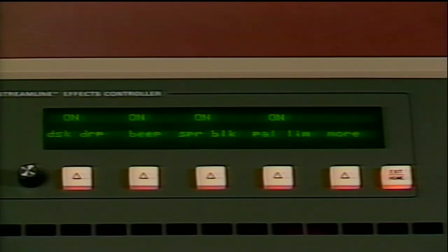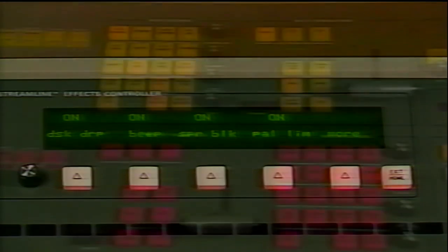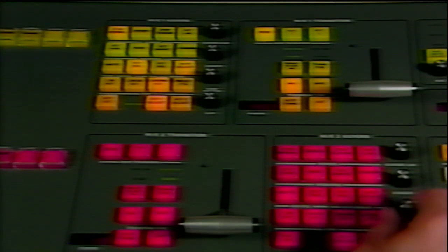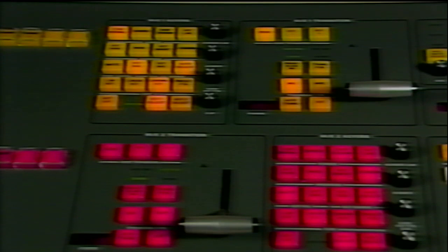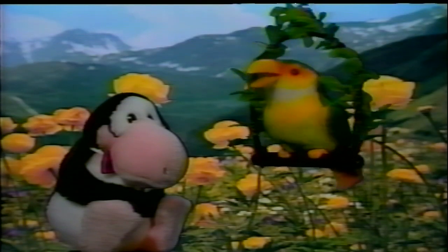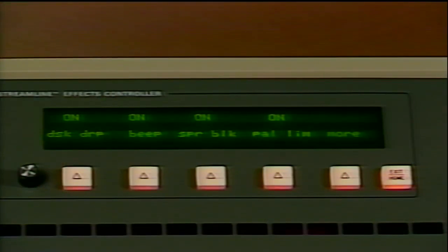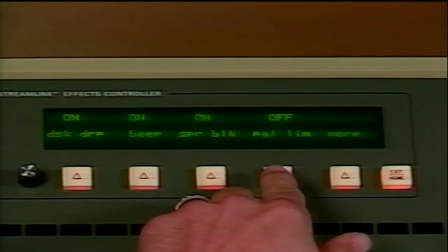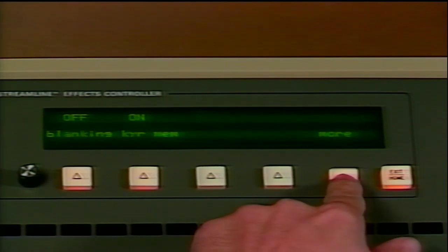The next Enables function from the Personality Programming menu is Super Black. The keyers in the Model 200 switcher have enough range to key from an input containing Super Black at blanking level. If the switcher being used is set for either NTSC or PAL-M standard, Super Black matte signals can also be generated in Background Generator 1. The PAL limiting function can be turned off, but the resulting colors may violate television standards in some areas. The blanking function will normally be left on.